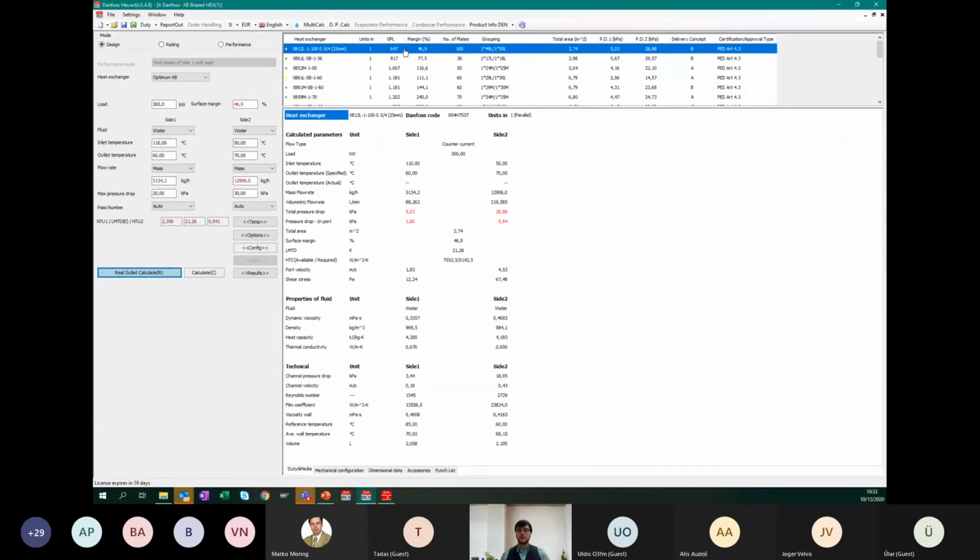Because when you have a symmetric application, as you see, I just showed you a very simple example. By just 2 kilopascal extra, I can make my heat exchanger already smaller and cheaper. If I add even more, like 8 kilopascal, I make it much cheaper. So please look at this as well when you're dimensioning systems, because what is happening is the primary pressure drop is increasing.